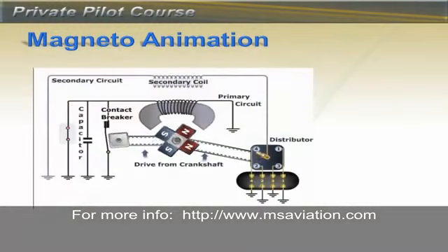So here is an animation of one of the two magnetos. Notice how the magnet is spinning along with the contact breaker and distributor. These are all timed together. The distributor connects to the spark plugs for each of our 4 cylinders, which are represented by number in the bottom right of the animation. The spinning of the magnet across the coils causes a spark.